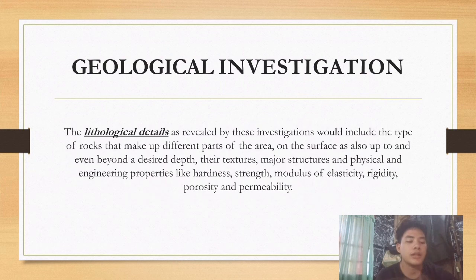The lithological details as revealed by this investigation should include the type of rocks that make up different parts of the area on the surface, and also up to and even beyond a desired depth. Their textures, major structures, and physical engineering properties like hardness, strength, modulus of elasticity, rigidity, porosity, and permeability.